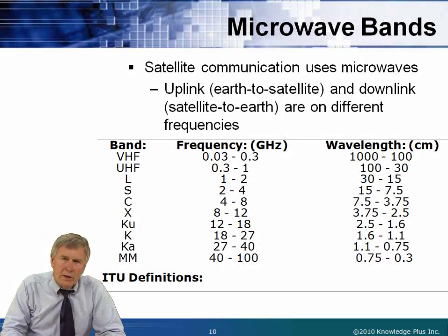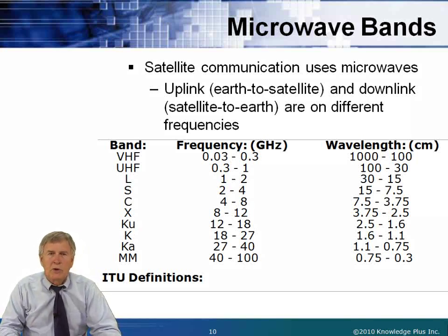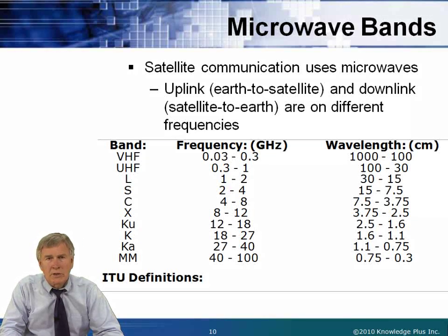And the game we have to play is that since we have to talk to the satellite, we want to use frequency ranges that minimally affect the radio signal to and from the satellite. So VHF ranges are more apt to interact with the Earth's atmosphere, so they're not ideal. Very high frequencies, millimeter wave technologies that you see listed there, sound good but have a phenomenally high path loss, so those don't make any sense either, except in certain applications. But for transmitting to and from the surface of the Earth, we don't use those.